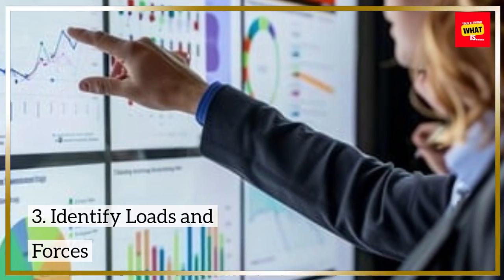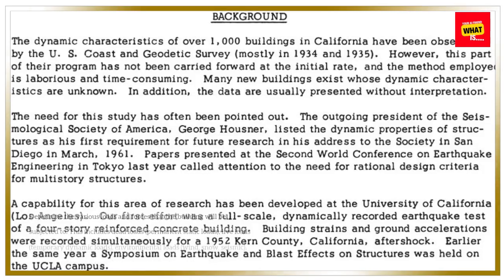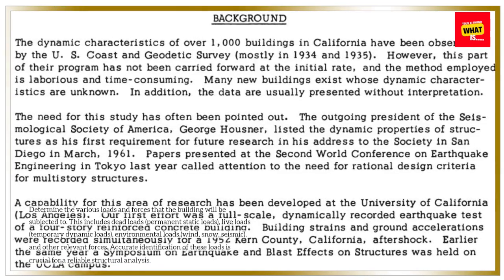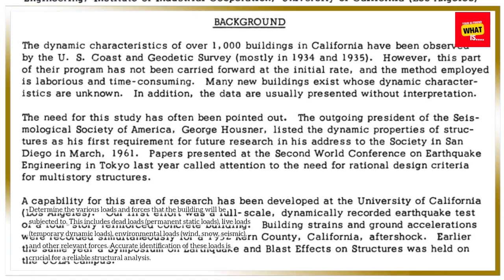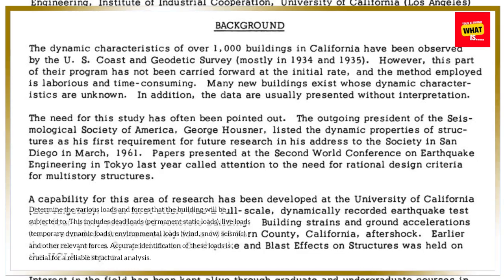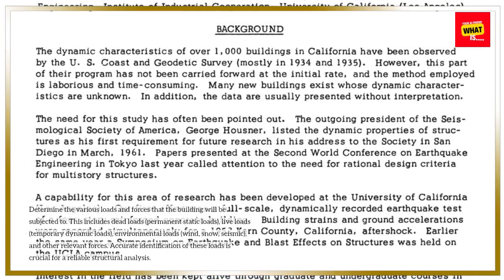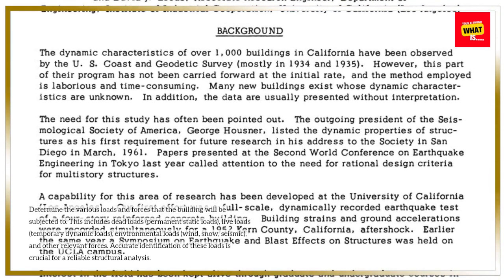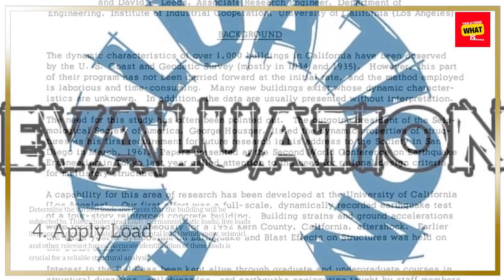3. Identify loads and forces. Determine the various loads and forces that the building will be subjected to. This includes dead loads, permanent static loads, live loads, temporary dynamic loads, environmental loads, wind, snow, seismic, and other relevant forces. Accurate identification of these loads is crucial for a reliable structural analysis.